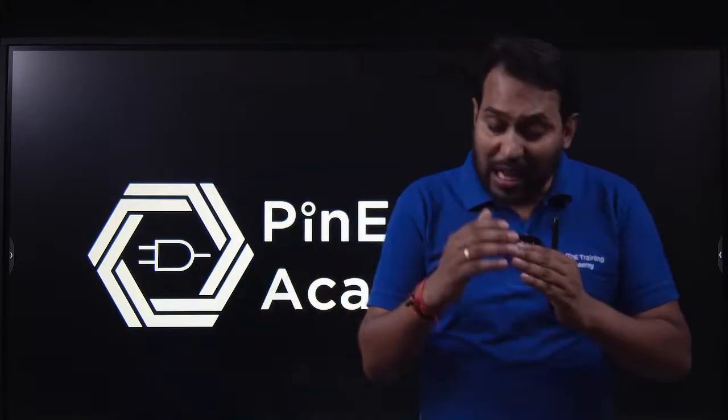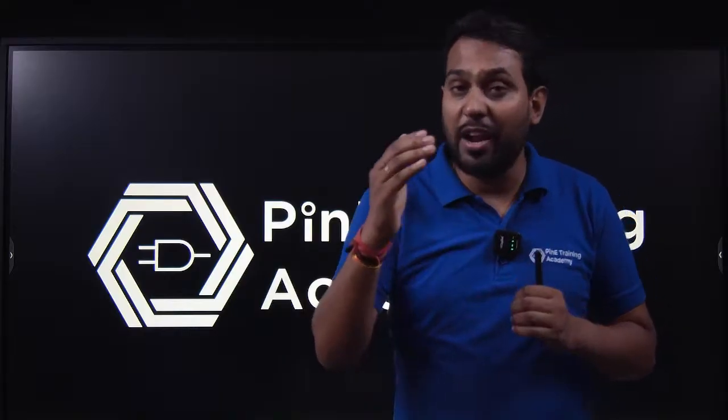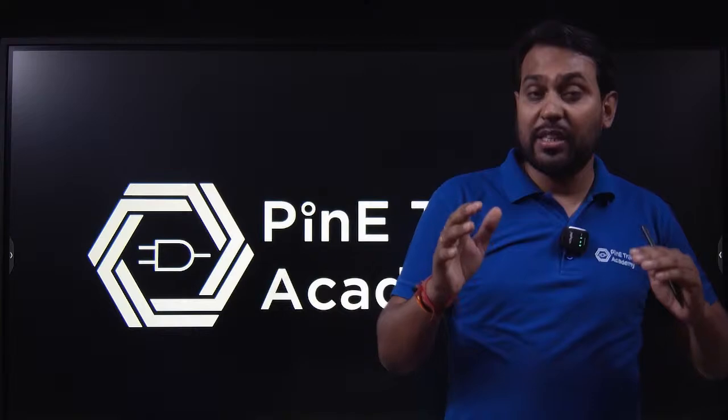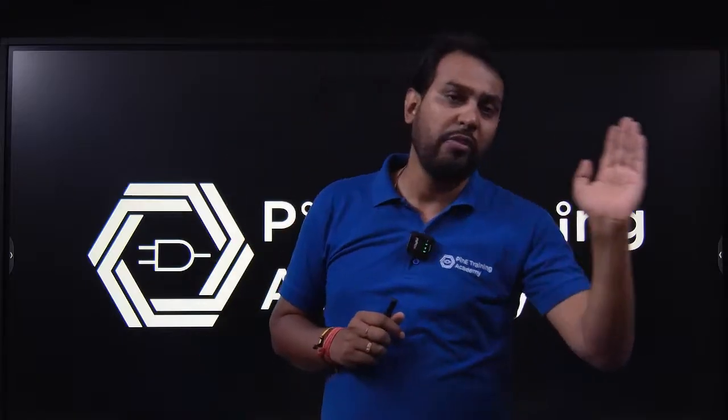So you will extract these capacitors and find them. The schematic provides some simulation. The same simulation I will run for the layout. If both differ by 5% or 10%, it will be okay. But if the difference is much higher than 10%, we will change the layout or we will change the schematic. So after the post-layout simulation, if everything is okay, you go for GDS, that is graphical data system or graphical design system, for tape out. If this is not okay, you go back to the layout or to the schematic design.